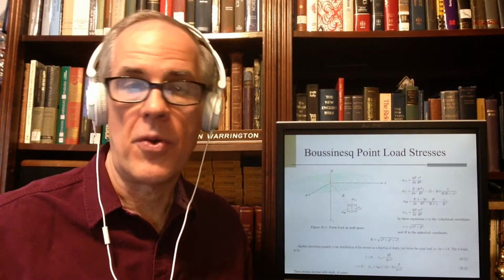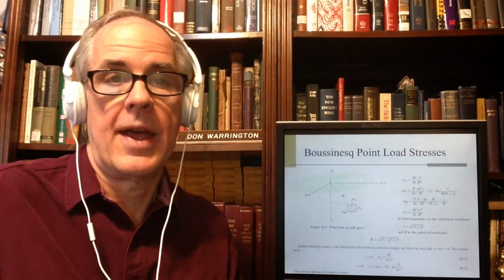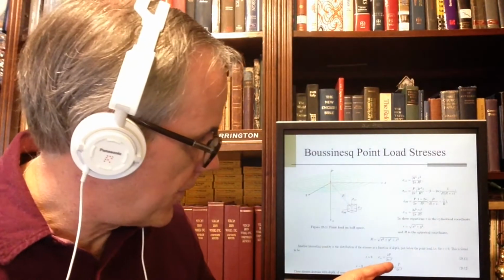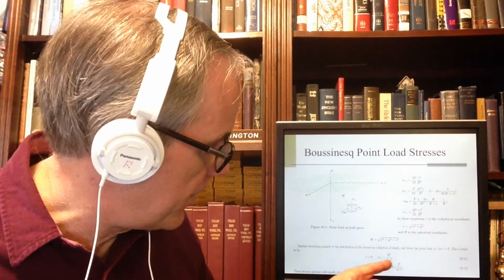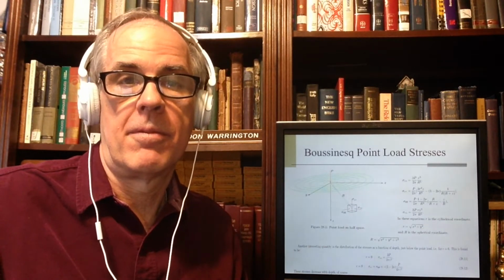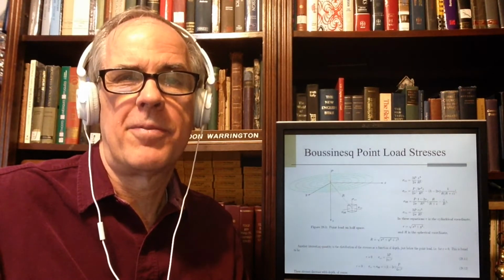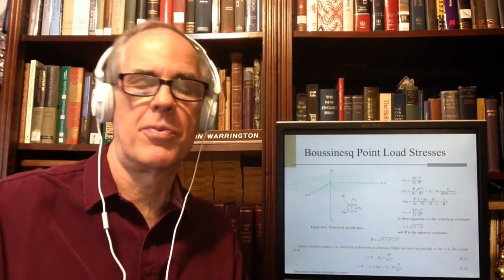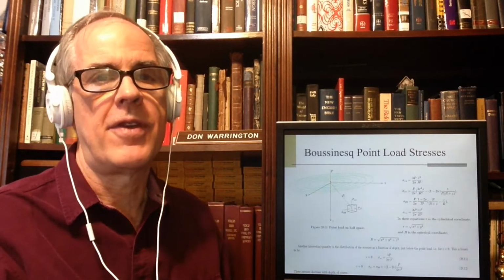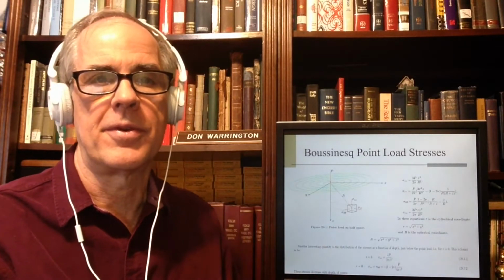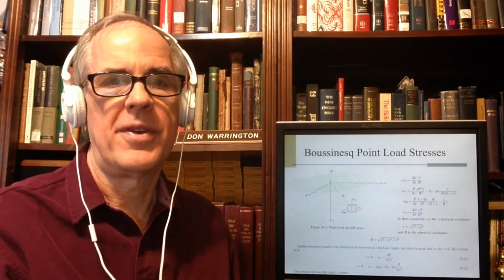Now, you will note that when Z is equal, let's look at these, for example, make it a little simpler. When Z is equal to 0, all these stresses blow up. That makes sense because true point loads, loads with an infinitely small footprint, just to try to use an expression, don't really exist.